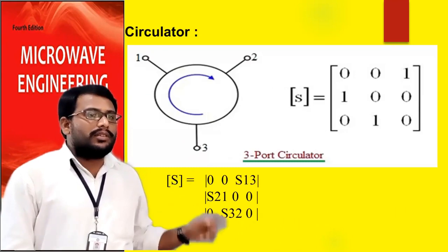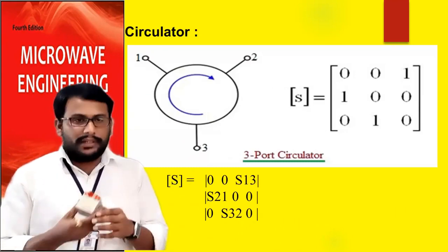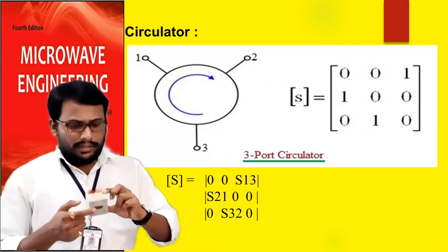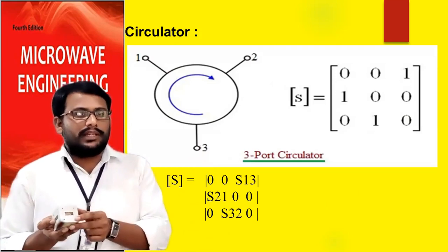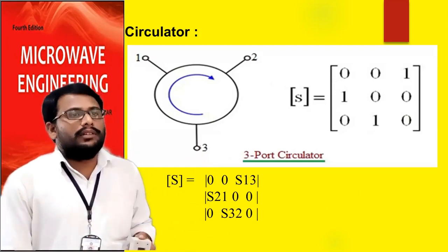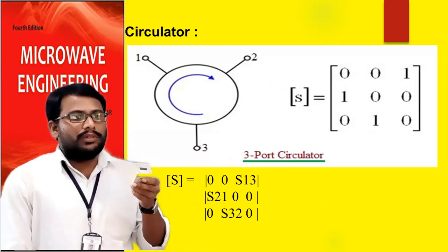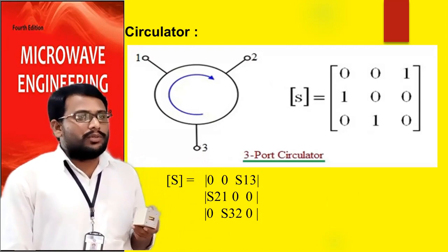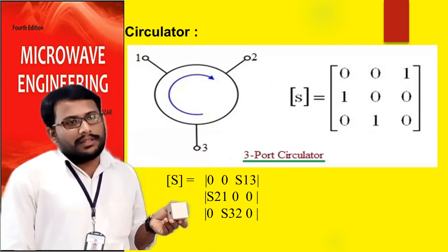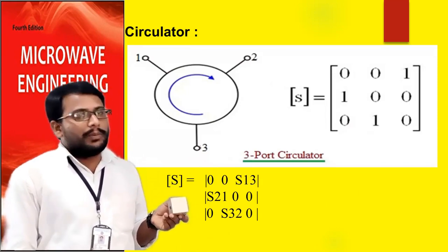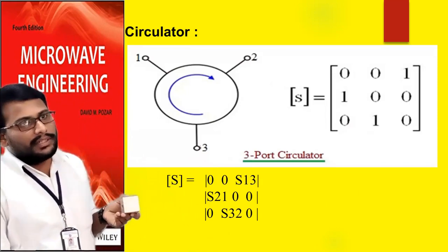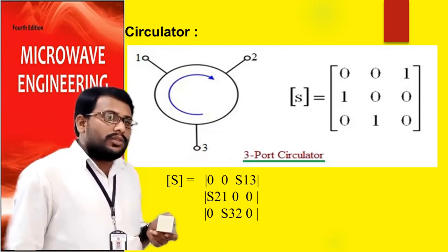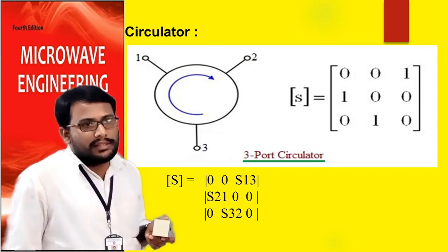Let's go for the circulator operation here. Let me show the circulator. See, this is how the circulator looks. It has port 1, port 2, port 3, so three ports. See the diagram here. If you connect port 1 to the input side, the frequency meter side, port 2 acts as an output port. Port 2 is connected to the detector mount and CRO, and port 3 is connected to a matched termination. So you have to change the ports in this cyclic manner.